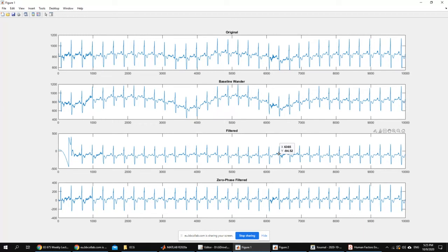I think this will be a little bit difficult for you to do, so I would suggest that you use zero phase filtration, so that you can get rid of both the transient and the shift. The use of zero phase filtration will give you an idea about how this filter is doing.